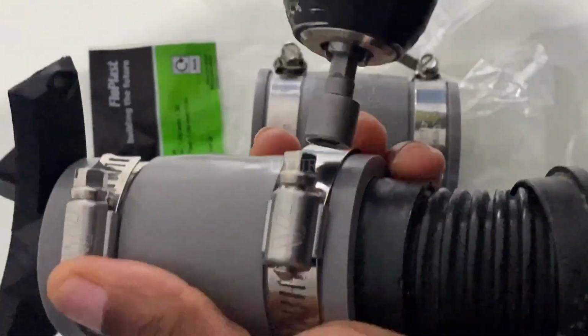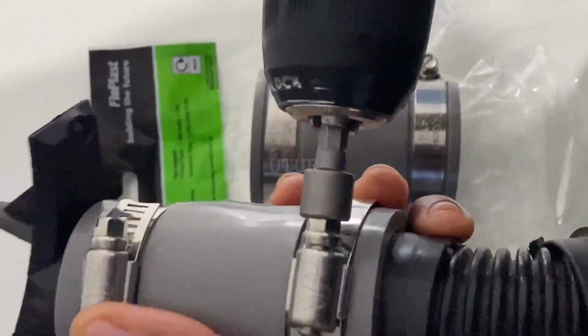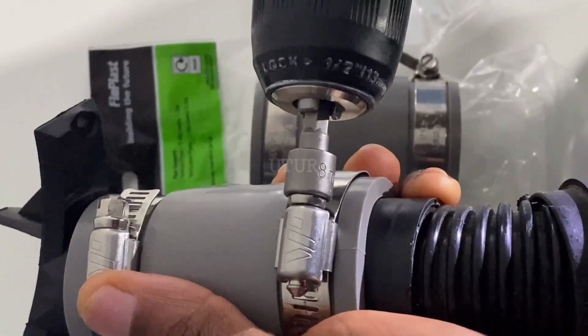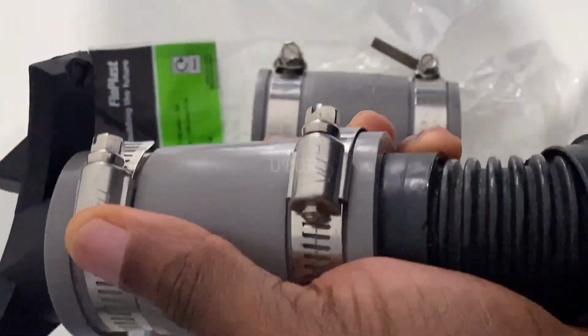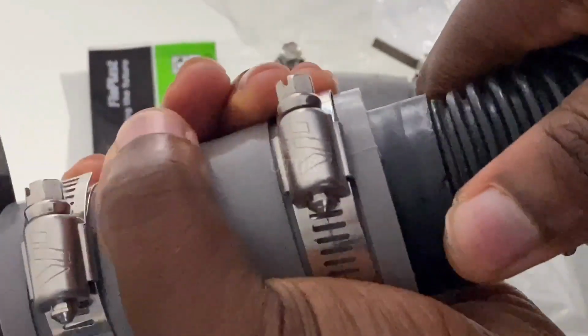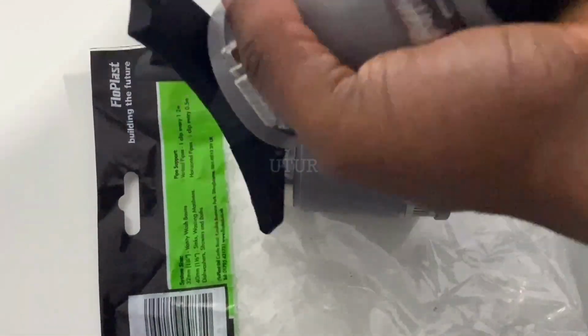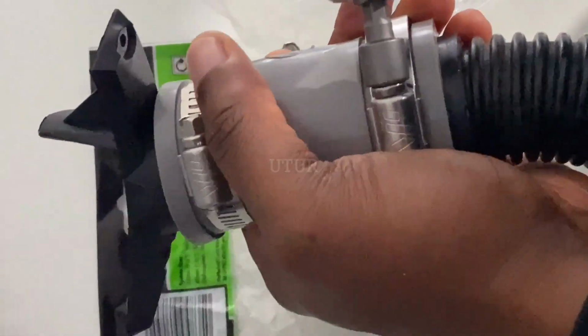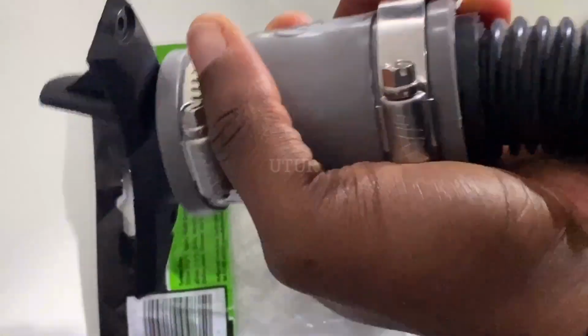Okay. And if you're not able to push fit the flexible hose into the coupling, loosen the knot. Undo the knot anti-clockwise, step by step. You can see it's got steps in there, so you'll be hearing the clicking sound as it undoes each step. Okay. When you've got more room, push fit the flexible hose into one end of the coupling. Okay, then torque tighten it, to prevent debris from escaping through any apertures.